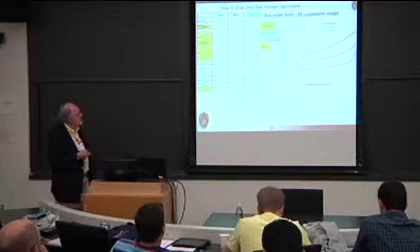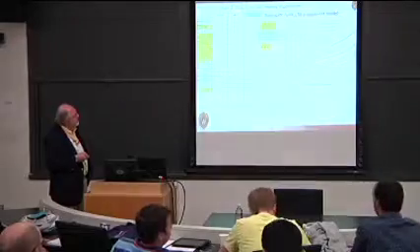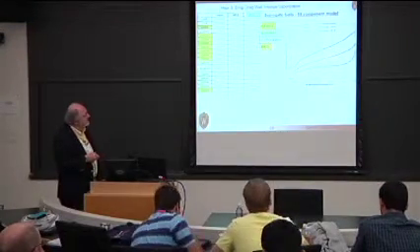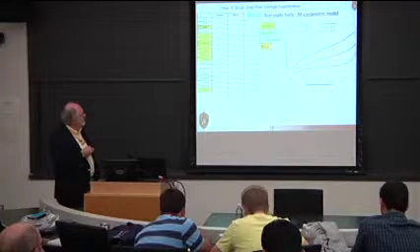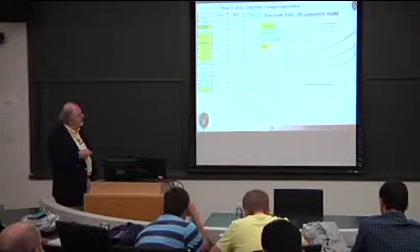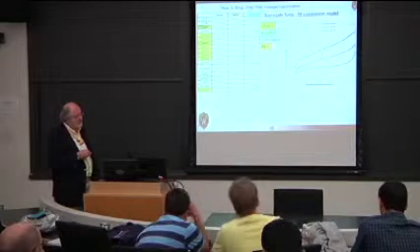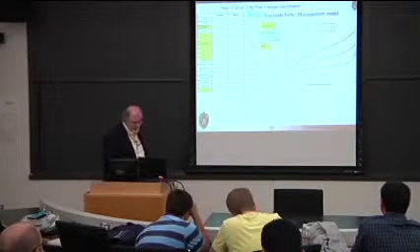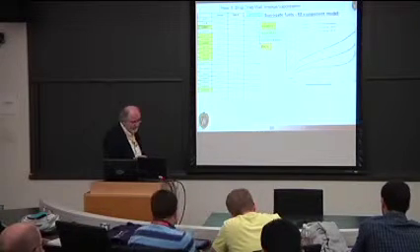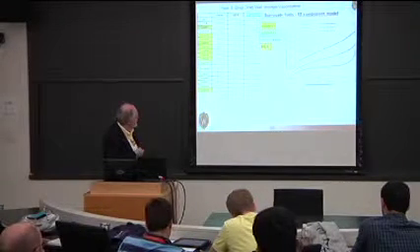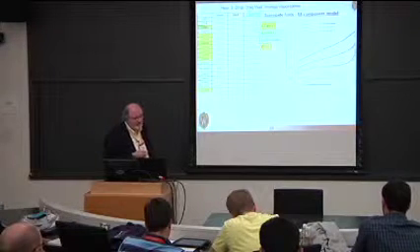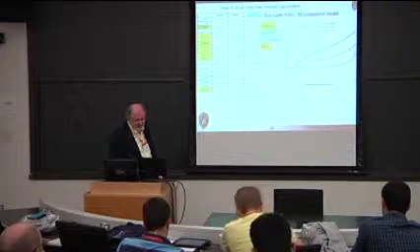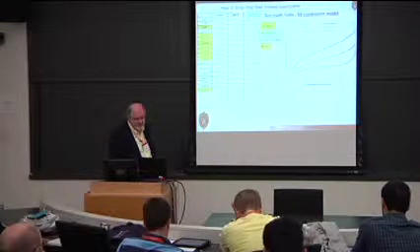those different fuels. So here you see for diesel, the black, and the Jet A, JP fuels, the amount of each of these components that would be necessary in order to represent this distillation curve. So that's essentially the approach we're taking in our modeling now, is to come up with a list of surrogates that we think characterize the fuel sufficiently that we can represent the physical properties of the fuel.